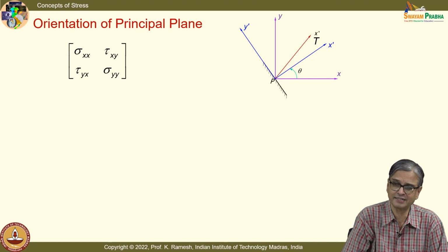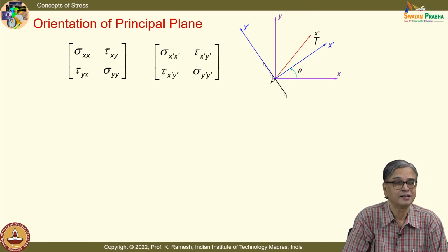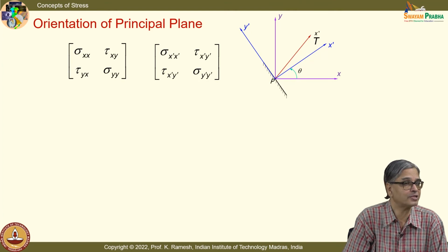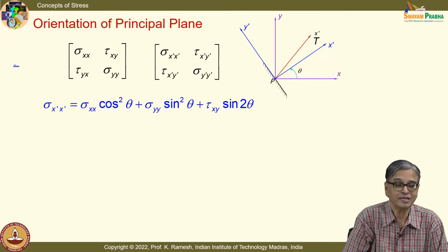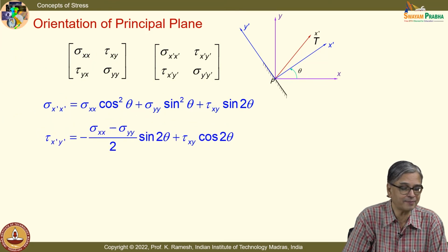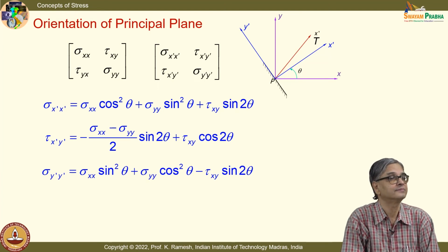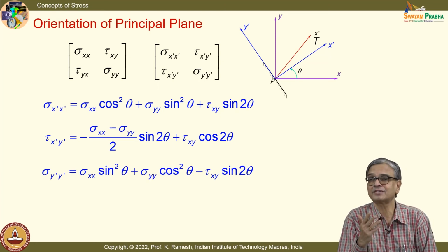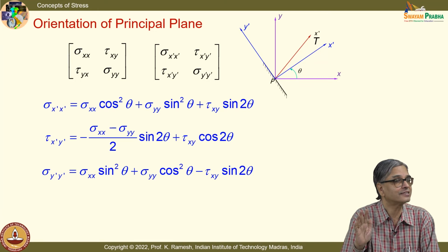Now, I said I have to find out the orientation of the principal stress plane mathematically. That means I should apply the condition mathematically. What is the definition of a principal stress plane? On the principal stress plane, you cannot have shear stress.